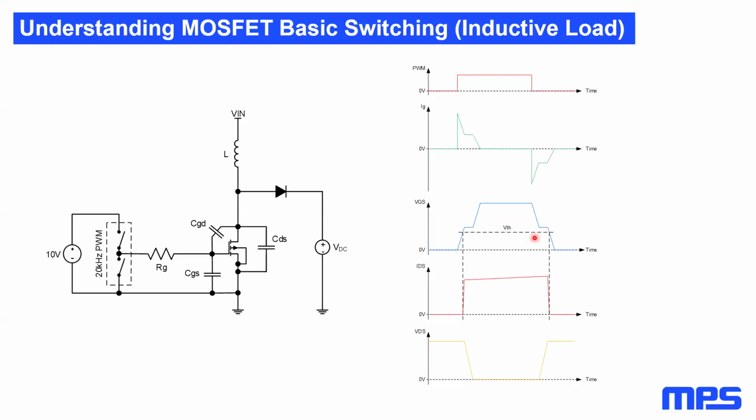The MOSFET is in its linear operation, and the declining gate to source voltage causes the current in the drain to decrease towards zero. Meanwhile, the drain voltage is steady at the output voltage level, and the rectifier diode is forward biased. The last step of the turn-off procedure is to fully discharge the input capacitor of the MOSFET. VGS is eventually reduced to zero.